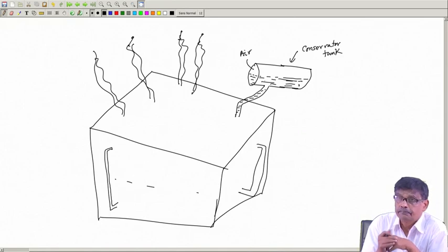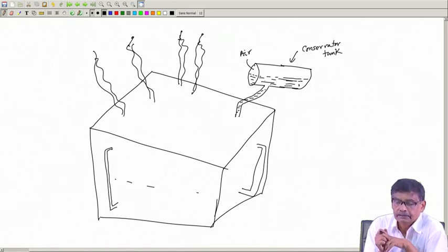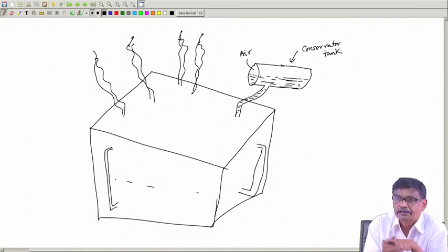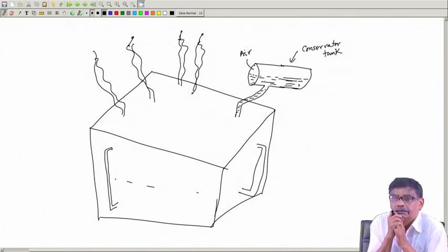Tank is a steel tank. So, it provides insulation. Also among the turns, as you go from one turn to another, there is a voltage difference, there exists voltage per turn. Therefore, a good insulating material we have provided. Air is also a good insulator, but this oil will be much better.